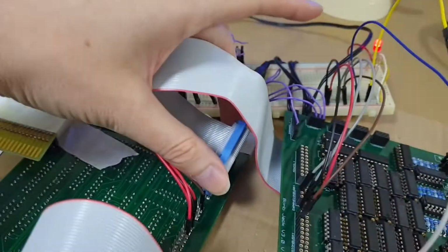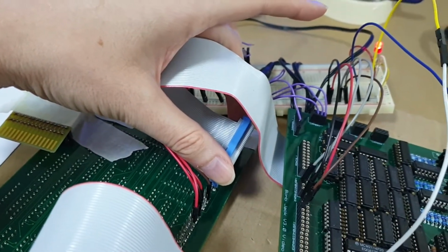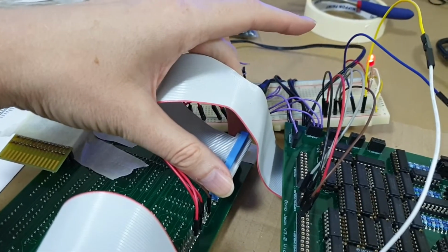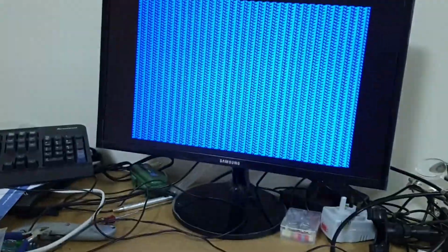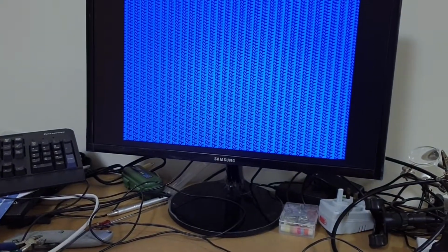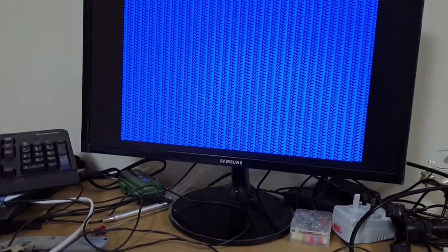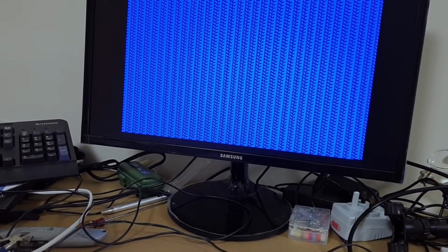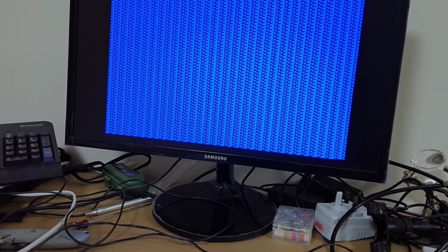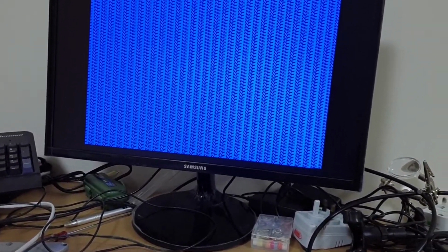Another short update. This is just like a build log, really, or a debugging test log. That's what it's turning into. So I've almost pressed down this cable here, and I've made sure that the pins are all round and located properly. I'm just about to press it down. The video signal is stable, but now when I start to engage some of the pins further up the header, so at the moment I think 1V and 1H and maybe 2H and 4H are engaged, because I'm starting to see the pixel rows come in for the character.